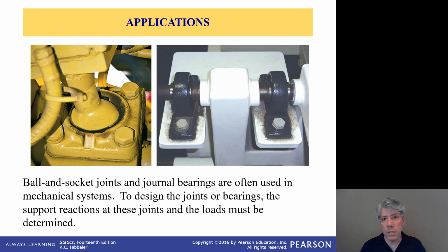When we model these in statics, we often neglect the thrust loads, the horizontal forces. There's a tremendous variety in the actual types of bearings internally. Some of those are not made to take a thrust load, in other words, a load along the length of the shaft, and some are. So there's some nuance in the bearing, but for the sake of analysis, we usually assume that there's no thrust load. We also assume there's no moment.